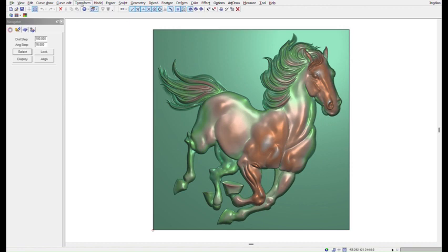And now you go to the model tab, in the transform, and first you have to select the maximum z to x y. Okay, now the total depth is minus 39.9. It shows the 40 millimeter depth has appeared. Then you have to be aware of that minus 40 depth. And then you go to the sculpt. Okay, now almost finished.